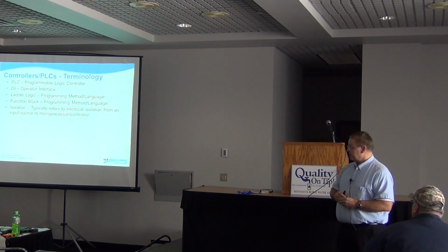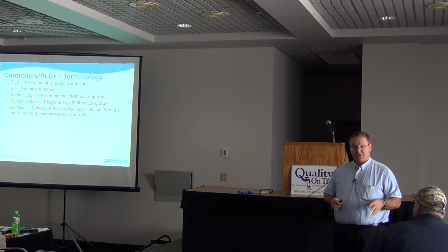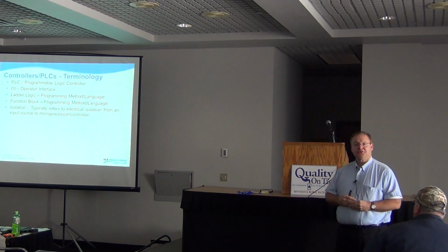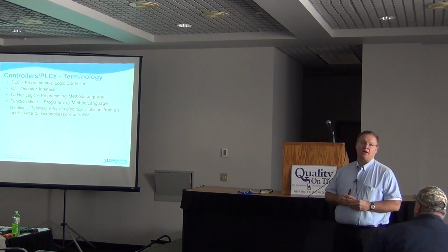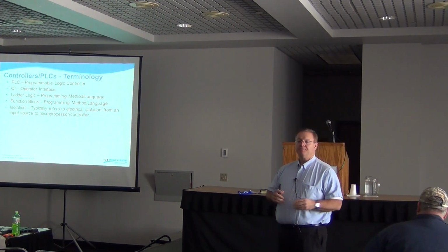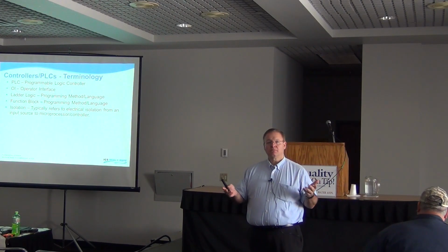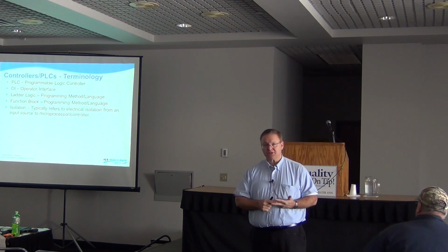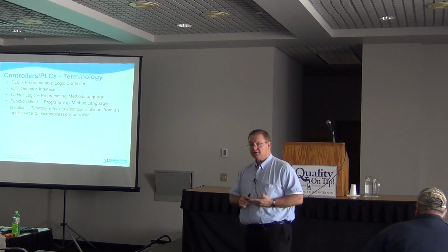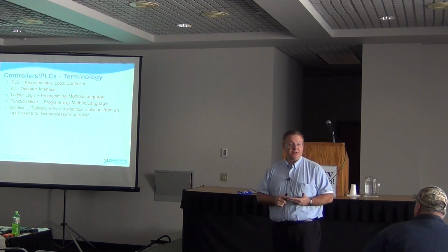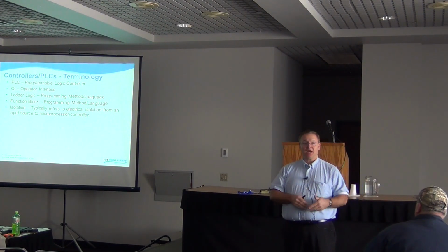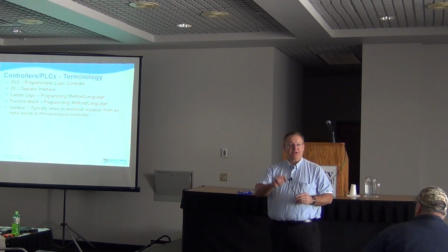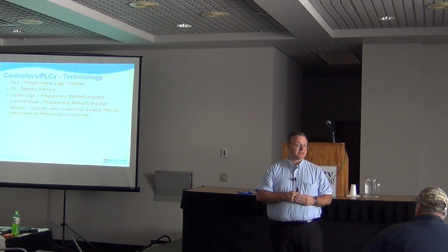To program PLCs, you're typically using ladder logic. I'm sure you've all heard of ladder logic. It's pretty commonly used. And most PLCs also have the capability to be programmed in a function block. And ladder logic, if I were to take, let's just say, a 4-stage alternator with first on, first off capability, pump fail replace logic built into it, it would take me 273 ladder logic programming elements to do that. So as you're looking at this logic, you're going to see rungs and rungs and rungs and rungs of data or logic in there that represents that specific function.